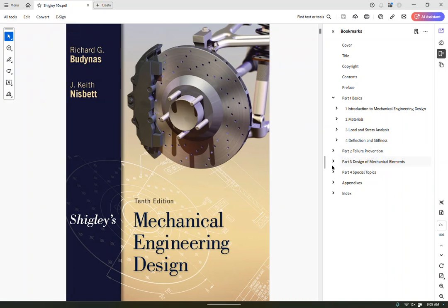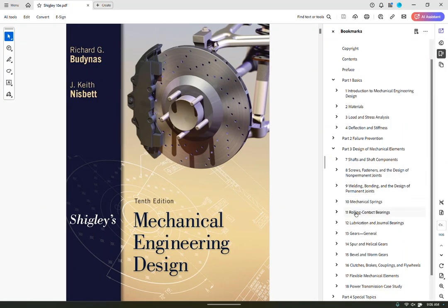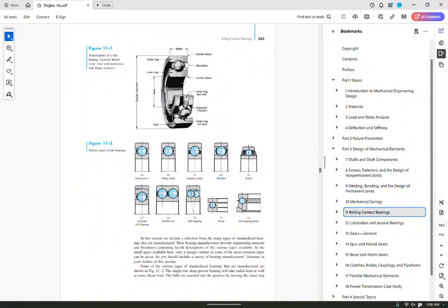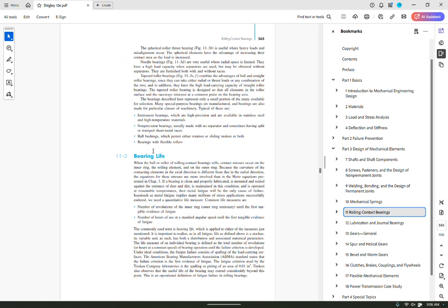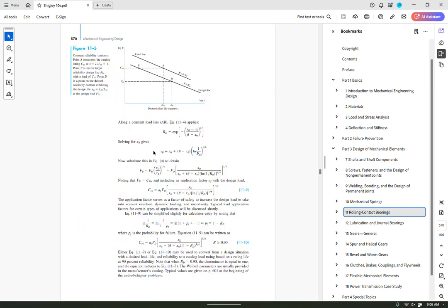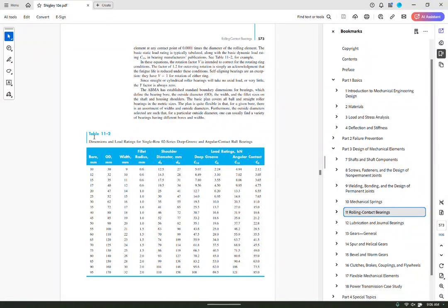Yeah. Oh well. So here in chapter 11 is our rolling bearings, and they give you better dimensions of what bearings look like. But the bore diameter and the width and how tall they are as well, we don't care about that, are established by a family of numbers. Let's see if we can get to them. Okay, so here is the table, and so here's the bore. That's the inside diameter, so that's the one that would match up with our shaft. They need to be the same diameters right here. But we also have the width of them. They're established by these being 02 series bearings.